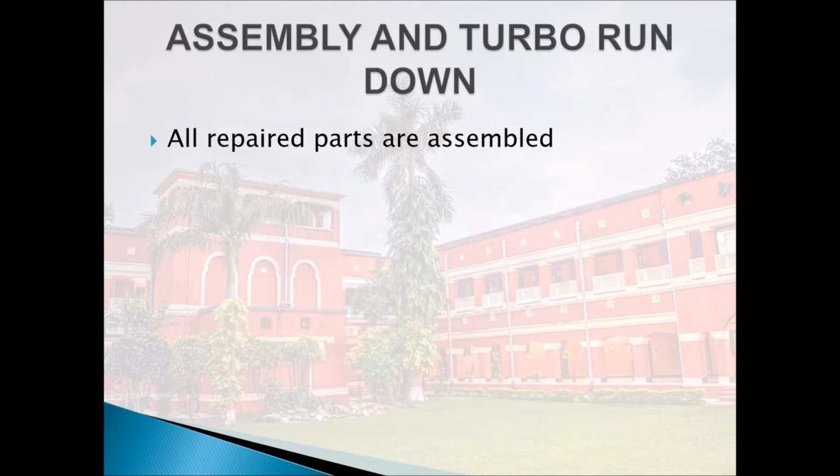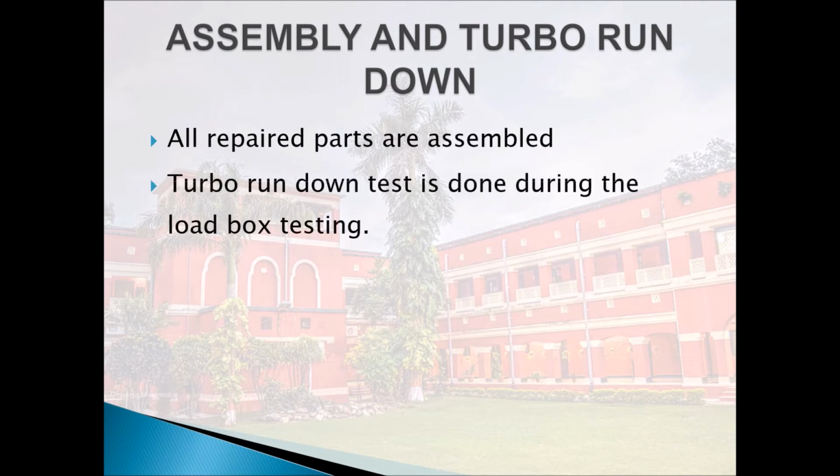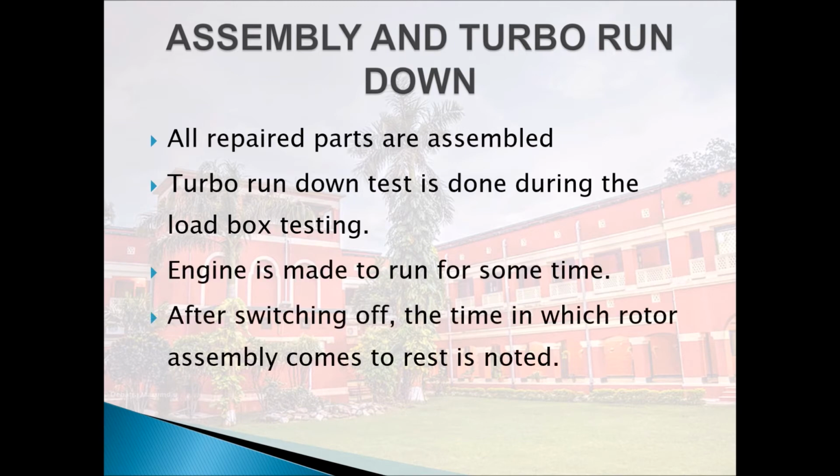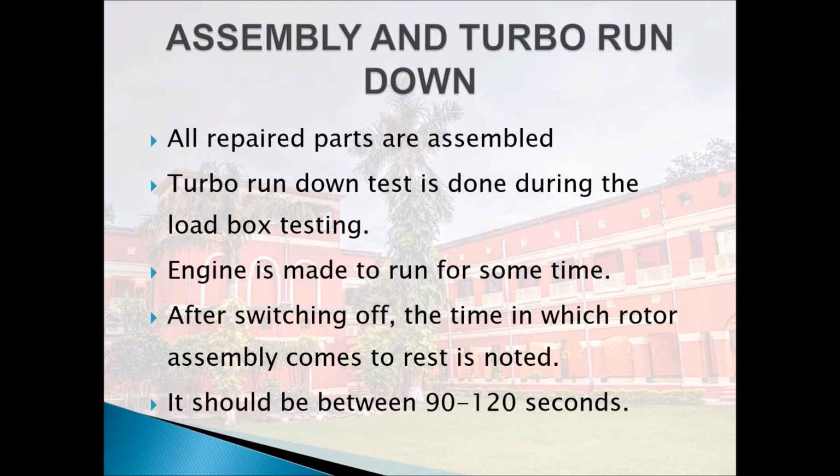After repairing, all parts of the turbo supercharger are assembled and the turbo rundown test is done during the load box testing. In this testing, the engine is made to run for some time and then switched off. After switching off, the time in which the rotor assembly comes to rest is noted. Ideally, it should be between 90 to 120 seconds.